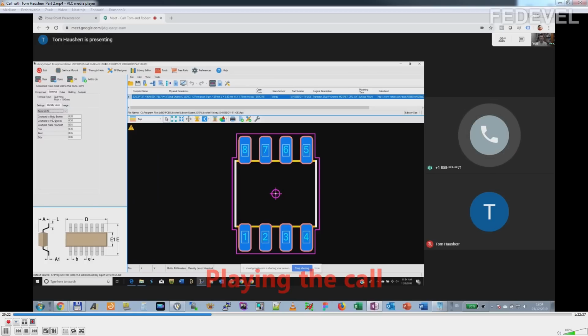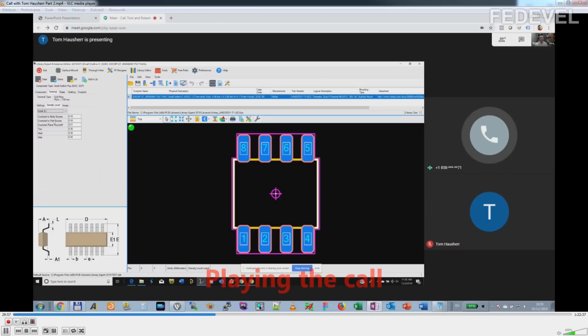And then you have your analog designs, your RF circuitry. Well, guess what? Those RF engineers are saying that the least amount of copper is best for them. So I want the rock bottom least amount of copper. I want it to be reliable, and I want it to pass all my tests. But I want the least amount of copper, because more copper means I'm going to get more radio frequency problems and issues in my circuitry. So they go down to the least density level. This is for RF and analog circuitry, and cellular phones and handheld devices.